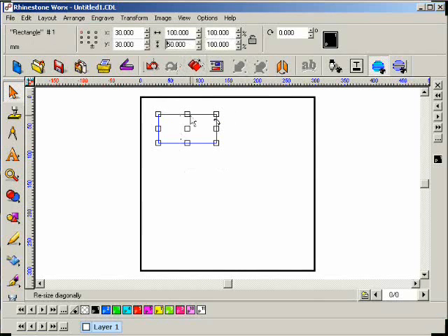And proportional scaling means that when I adjust, let's say the customer says I need this to be maximum 3 inches height, proportional. Yes. You would just type in the 3 inches or whatever, the 50. You want to make sure that this icon is locked. So if I hold my cursor over it and then I click down, and it's showing the lock, that means that if you change one of these values, say to 75, it would proportionally change the other, the height. And vice versa.